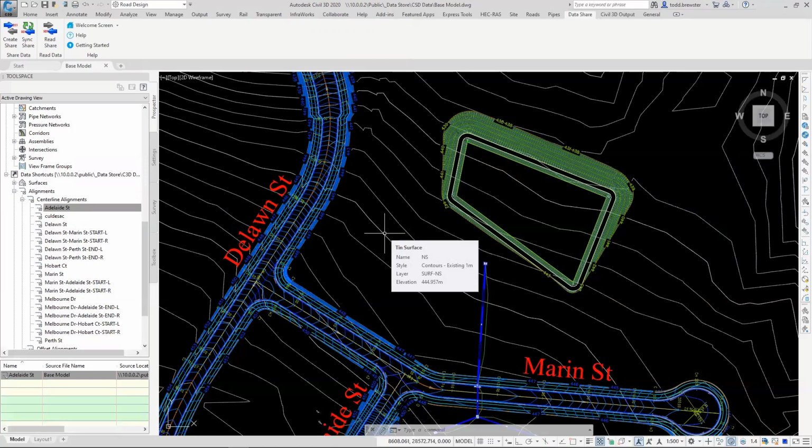The other one is, as Shane talked about, you could use the data shortcut editor and preemptively fix them if you knew that you deliberately shifted the locations of everything and you want to reconnect the data shortcuts because you know the new paths. Okay, that's it from me.